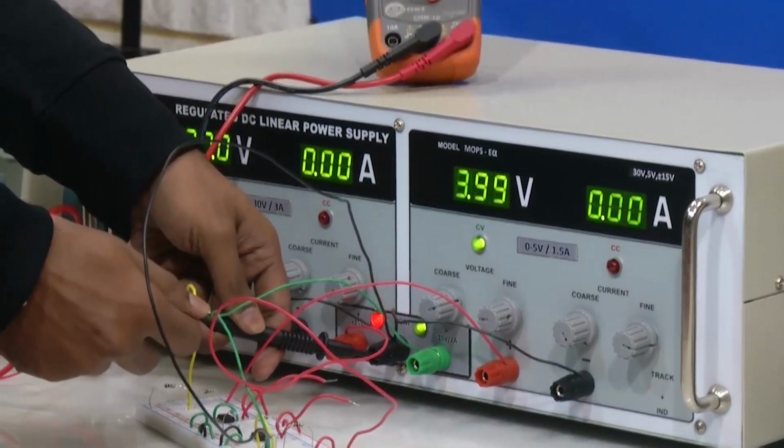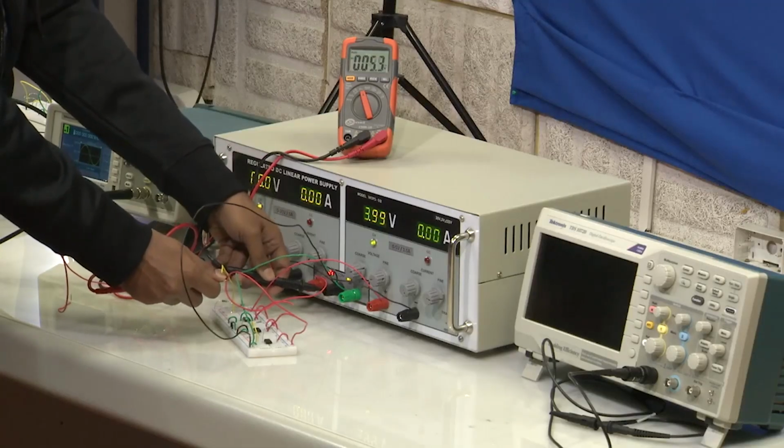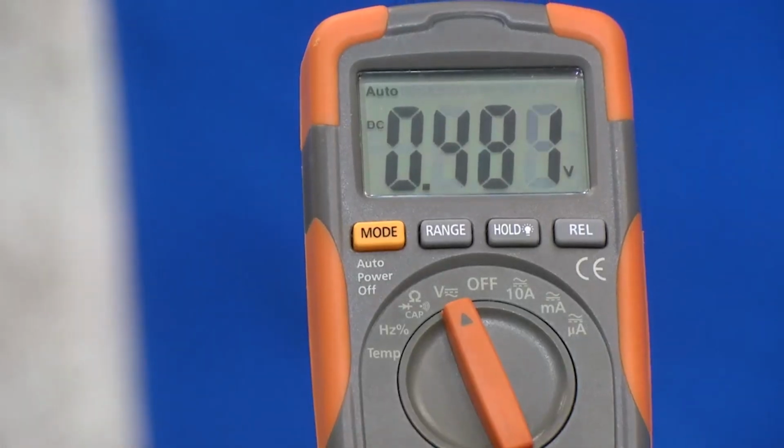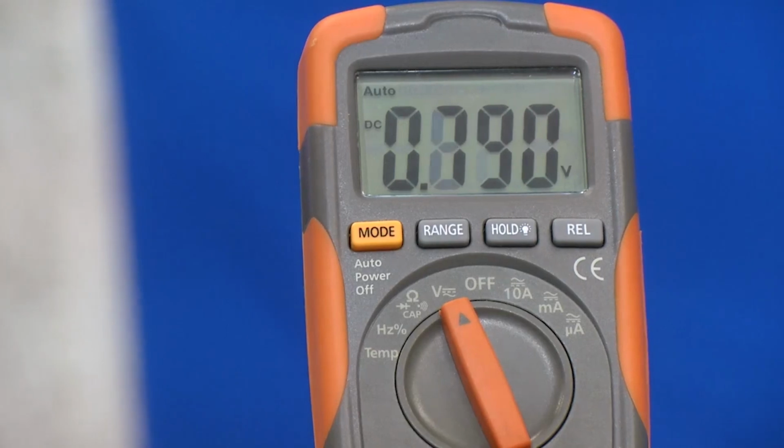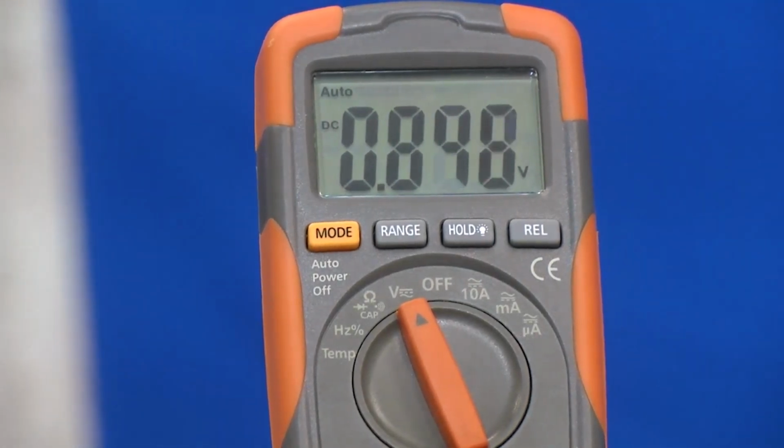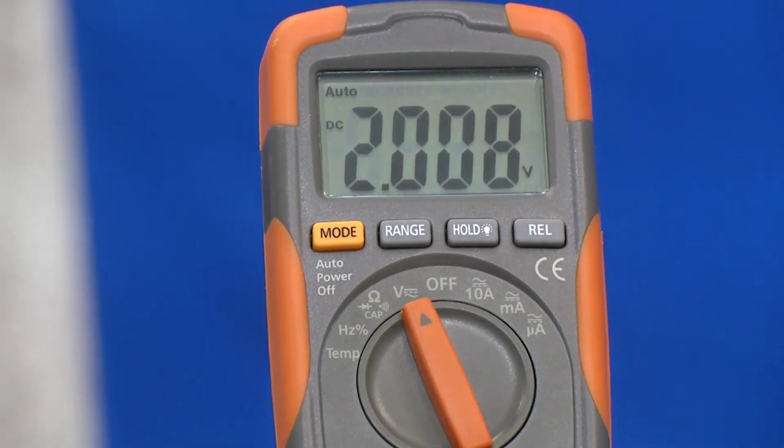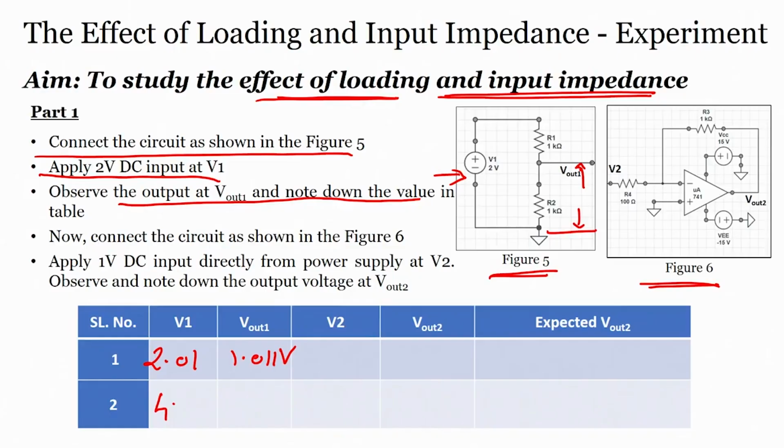and he is again measuring the voltage. What we can see is the voltage at the output is 2.007 volts. So, 4 volts at the input, 2.007 volts at the output. Understood? Very easy how to measure the voltage across resistors. So, this is a potential divider circuit.